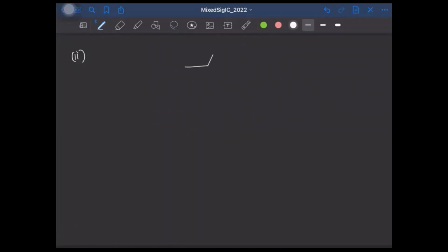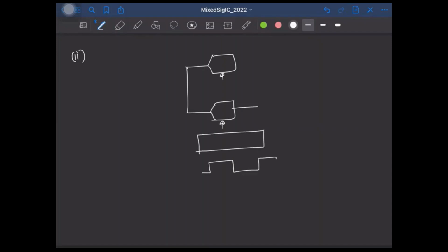You can have the first ADC and the second ADC. And the clock to the second ADC might come from another clock, which generates multiple delayed versions of the clock. Okay. And you can choose which of these clock signals need to be used for sampling, again by doing some digital calibration, right?